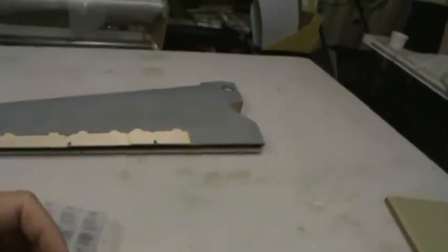So all right, somebody was asking about the flap standoff thingies, what I was going to do with those. I got the other molds closed up. No, they're not closed up as in ready to pull out. They're just closed up because I'm getting ready to go out of town for a few days, so I wanted to close them up to keep them from warping. But anyways, this is the original wing that I did the layup on, the really heavy 3-pound one. Everywhere you see HB is where I was going to put a hardwood block for the hinges for the flaps. That spar has now been moved forward about 1.5 to 2 inches.